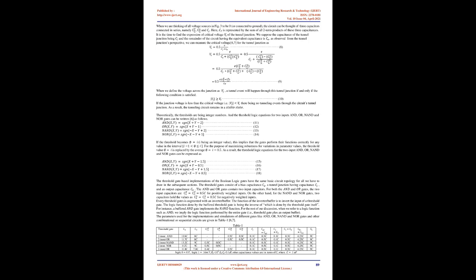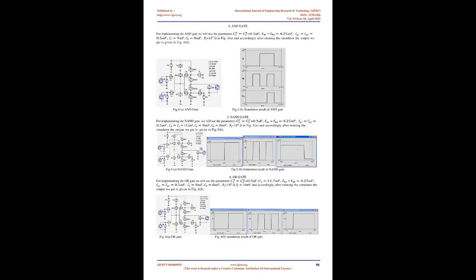2. Inverter. The inverter, depicted in Fig 2a, is made up of two SETs connected in series. The same input voltage is directly coupled to the islands of SET 1 and SET 2 through two capacitors, C_g1 and C_g2, respectively. The island of each SET has a size smaller than 10 nanometers of gold, and their capacitances must be less than 10 to the power of minus 17 F. The output terminal V_0 is connected to the common channel of the two SETs and to the ground via a capacitor, to put down charging effects.